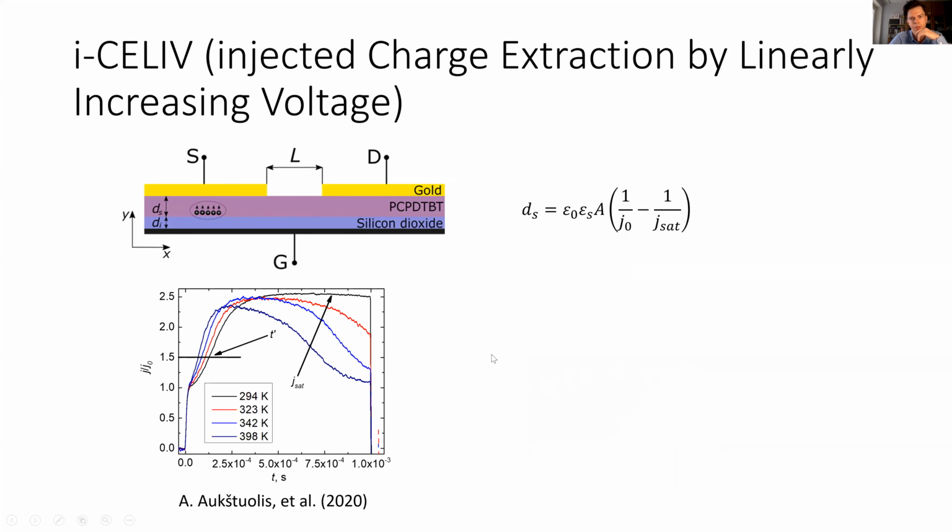So with these values, we can get the thickness of the layer. With this method, we can find not only the mobility of charge carriers, but also the thickness, without any other methods like spectroscopy, AFM or similar. And having this value, we can find the transit time of the holes, and then eventually find the mobility, which is in the direction perpendicular to the substrate.